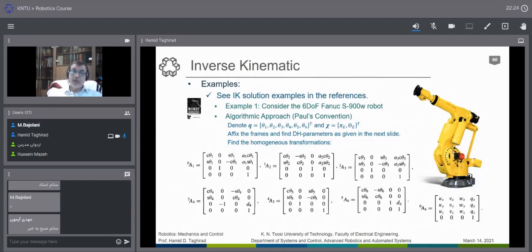As you go further, for the first joint, you have a motor here. For the second joint, which is in here, you can use the parallelogram, and instead of bringing the motor on top of the robot, you can use the motor on the bottom at this point, or even at this point, where you can simply have a symmetric point here.